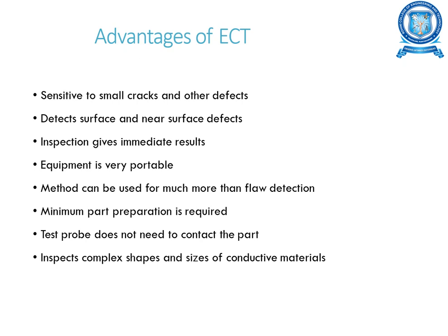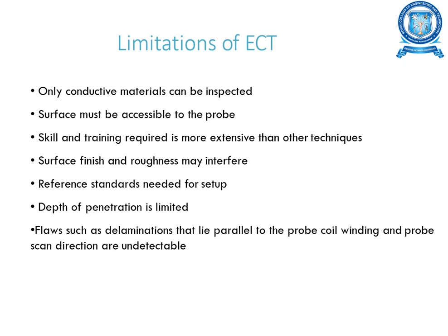The method can be used for much more than flaw detection, and minimum part preparation is enough. The test probes do not need to contact the part. You need not bring the test probes in contact with the material that you are going to test. Complex shapes and sizes of conductive materials can also be inspected by using this eddy current testing method.